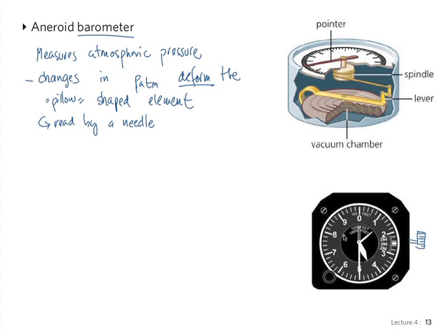If you're going cross country, say, flying between two faraway places, then everybody sets their altimeter to 29.92. So all the planes have the same reading, regardless of the atmospheric pressure. And if I know that the other plane is reading a certain altitude and I'm reading another one, we're not going to collide because we are calibrated to the same pressure. So you see, this is a very useful application.